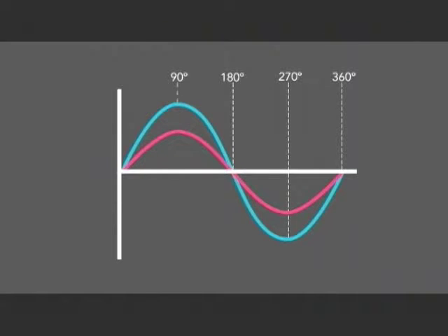The phase relationship between the voltage and the working current is the same. Both have the same basic shape, and changes occur in perfect step or phase. However, AC circuits usually have equipment that must be magnetized. That part of the current that is used to establish the magnetic field lags the voltage by 90 degrees.